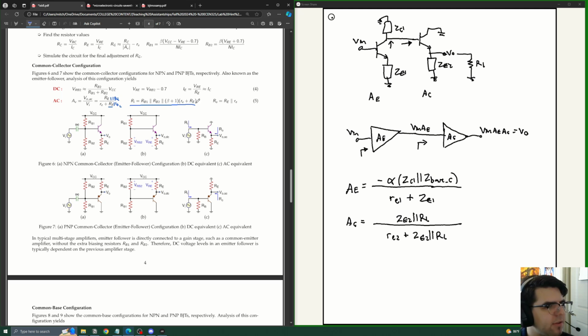And what's also nice is that the output impedance is especially low, which is useful for applications where the loads are really, really small, think about radio frequency applications. If you've taken 322, you might know how important it is to match impedances properly. Well, this is a case where it's nice because the impedance can be pretty low. We can get it to around 50 ohms or whatever we're trying to match, and that leads to a pretty good deal. So the source follower is very good for buffering your output, and is used amongst some other more complicated amplifier configurations.